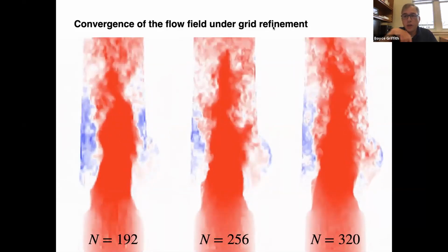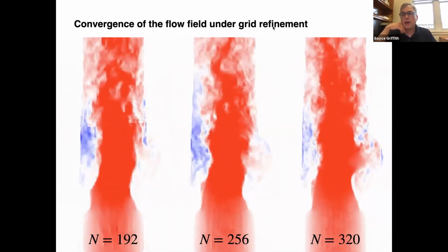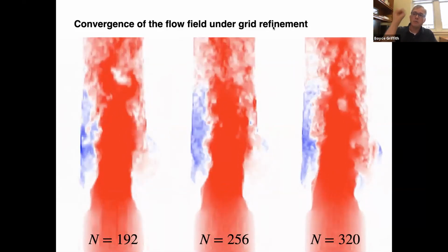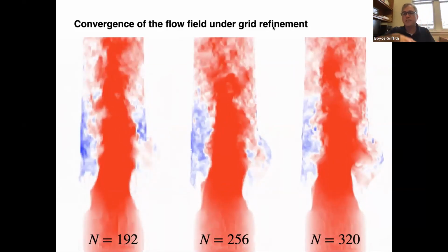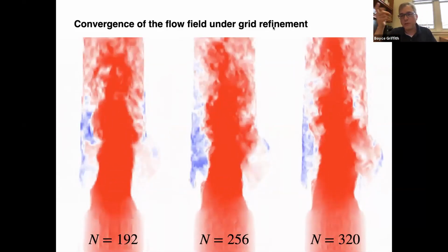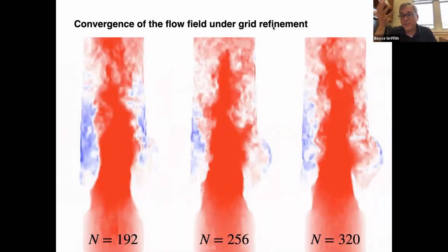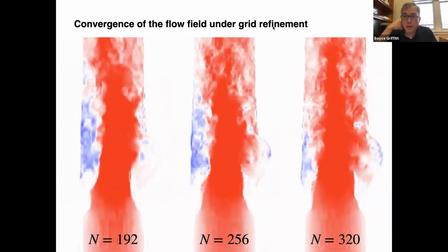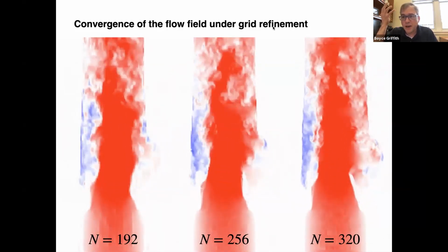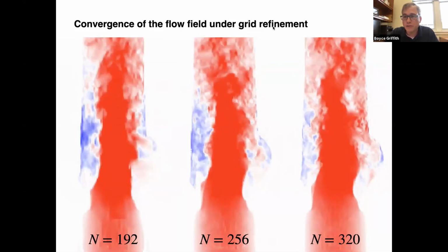Yeah, absolutely. The coupling that we use is like what I sketched out at the beginning of the talk. We use something more complicated than this, but basically we compute forces, we put the forces on the right-hand side of the Navier-Stokes equations, we solve Navier-Stokes, then we use the velocity to move the structure. So it's explicit coupling between the fluid and the structure. With the way that we're doing things, it's like using an explicit method for the structural mechanics, even if you're using a semi-implicit formulation for the Navier-Stokes equations.